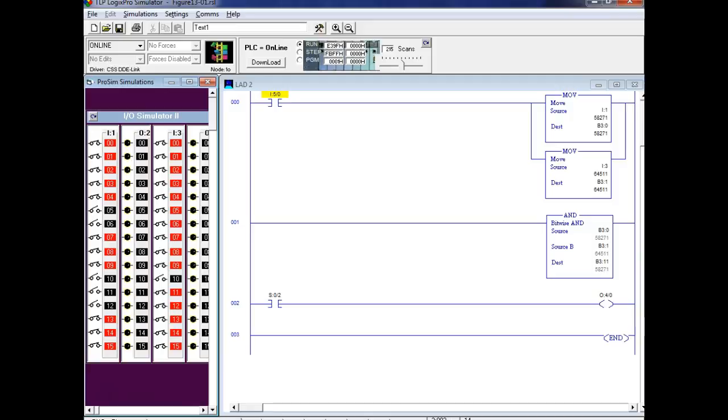Y'all understand what we can do? So right now, what's my integer math? My integer math is 16 bits, right? Or if we do a long word, it's 32 bits. But what if I did math and I'm dealing with positive numbers and I wanted to extend it up to 64-bit math? Could we do that?